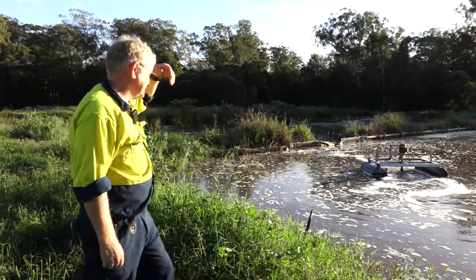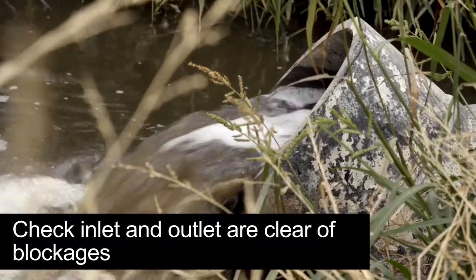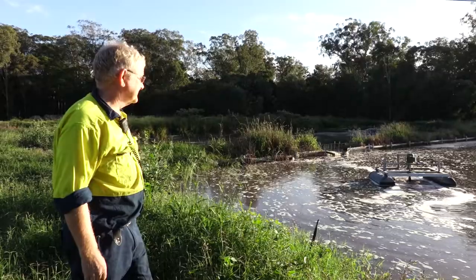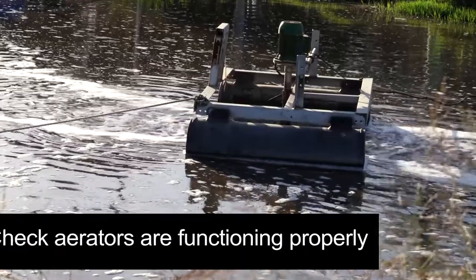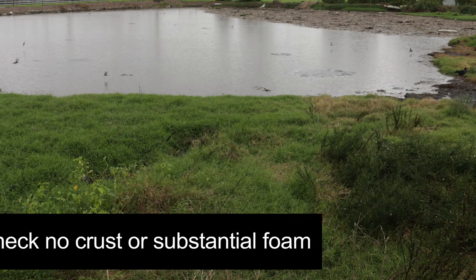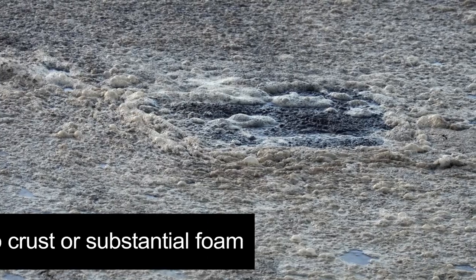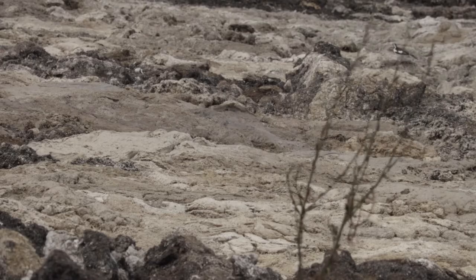Operators should inspect aerobic ponds at least once every week and confirm that the inlet and outlet are clear of blockages. If the pond is aerated, then they should also ensure the aerators are functioning properly. Unlike anaerobic ponds, you want to make sure there is no crust or substantial foam on the pond. Crusts prevent good aeration of the water and are a bad sign for aerobic ponds.